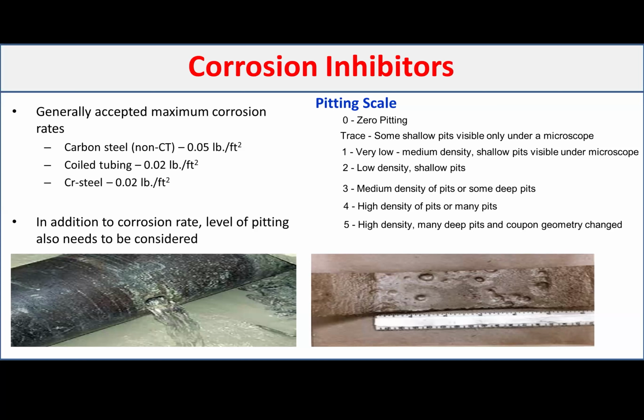you release it, you take the coupon and weigh the coupon after. You have the initial weight, you have the final weight, and between them, the acid will be corroding, so you will lose some metal. And you convert these weight losses into some sort of corrosion rate, which will be pound per square feet. So you know the coupon dimension, 1 inch by 1 inch. So you have the surface area, you know how many grams were lost, and then you have the mass over area converted to pound per square feet.